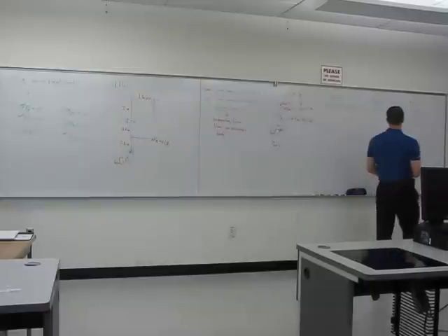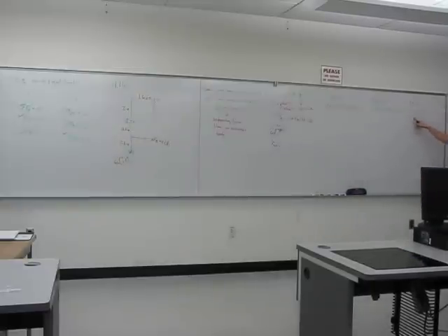So if you plug the number in for FB and FD, so put 4 in here, put 6 in here, you can solve this equation for FA. If you solve for FA, you should get 8 pounds. So it told us to find the reaction force, or the force exerted on the roller at A. Well, we found the magnitude of the force, so that's not good enough to express as the final answer. I assumed the direction up and to the right. I got a positive answer, so that means the direction that I assumed is true. So when I write the force vector, I can say 8 pounds angled 60 degrees up and to the right.